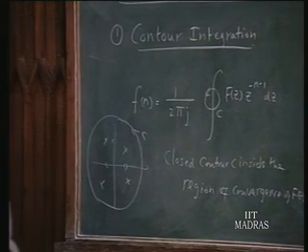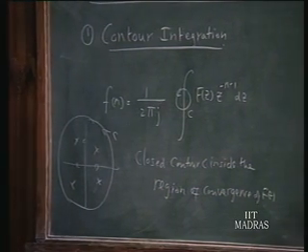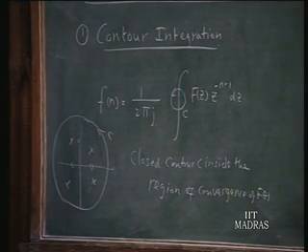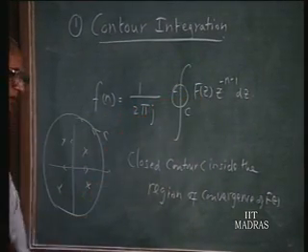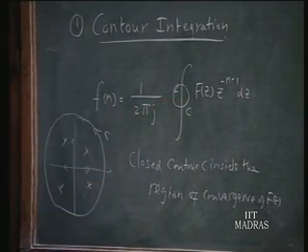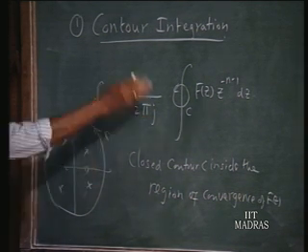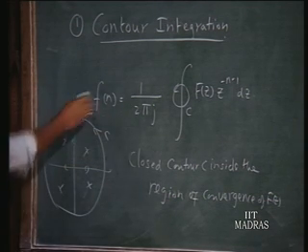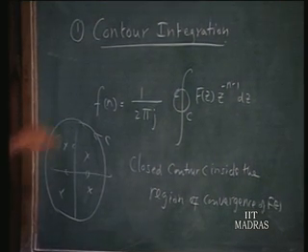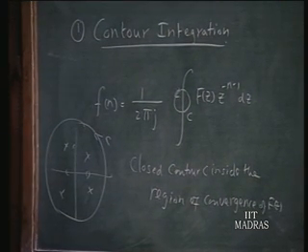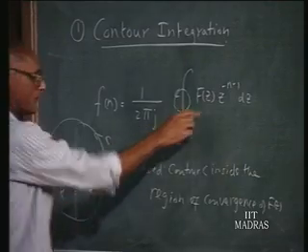Those of you who are familiar with integration in the complex variable situation form this function, find the residues of the various poles of this function inside this contour, and since we have got 2 pi j here, the sum of those residues will be your f(n). So this is a fundamental way of doing this, and one can also interpret this just as we have done in the continuous case as F(z).